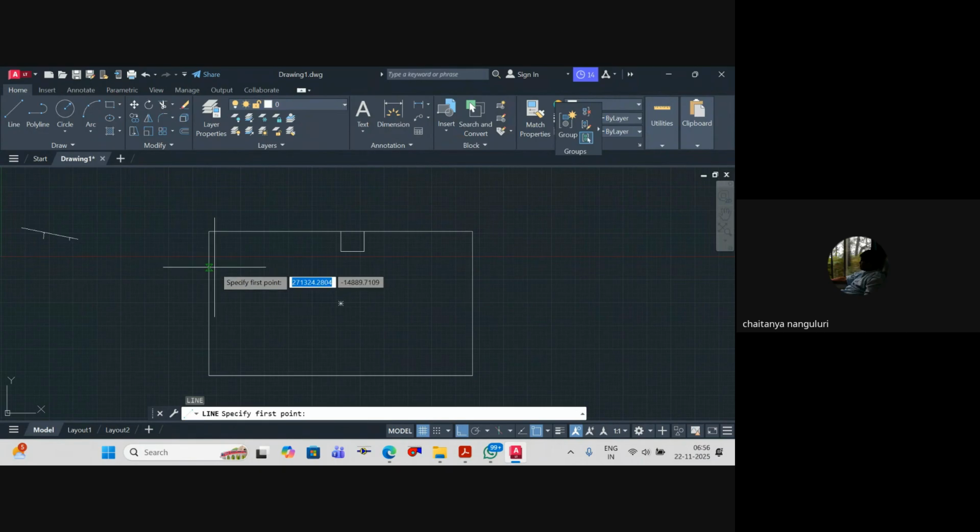But in case you have a false ceiling, if the space between ceiling and slab is lesser than 800, you need not install a detector, assuming you don't have any combustible materials. Cables are okay because nowadays we generally use FRLS cables only in most cases. But in most civil cases, they'll use wooden pattas for the supports of gypsum board. In that case you have some combustible material. But if you do not have any combustible material, then you can ignore it. If it is more than 800, your beam anyway becomes greater than 10%, right?